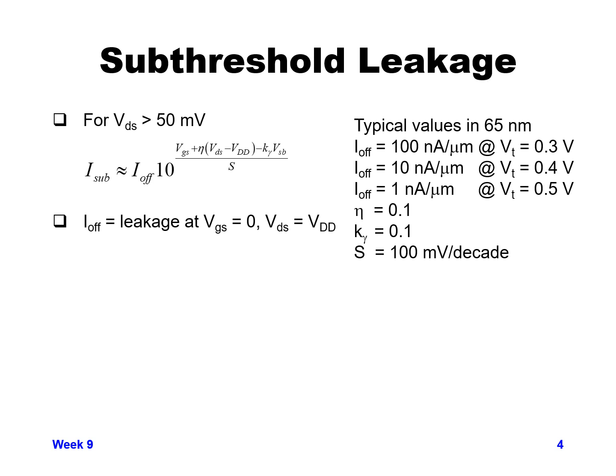That's one of the reasons they use multiple VT devices in a process technology. You might see a nominal VT, a high VT, and even an ultra high VT, in order to reduce your leakage as much as possible on non-critical devices.